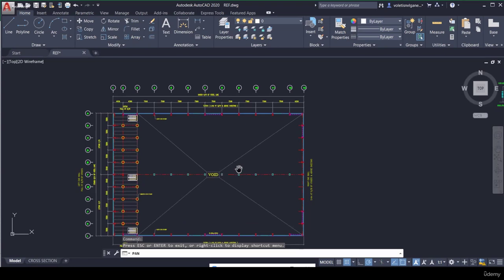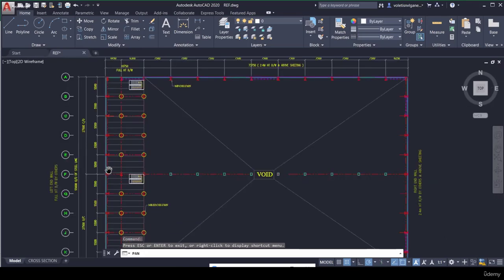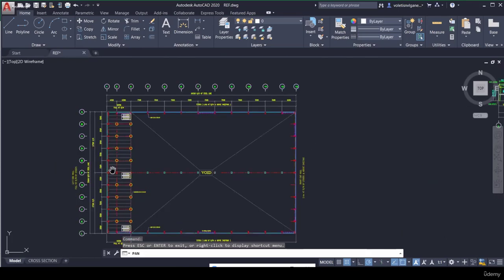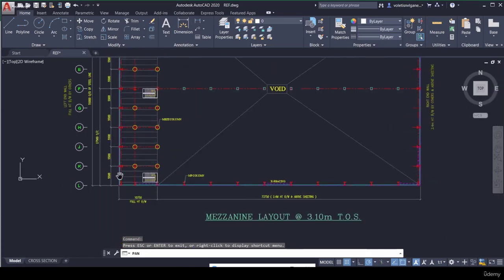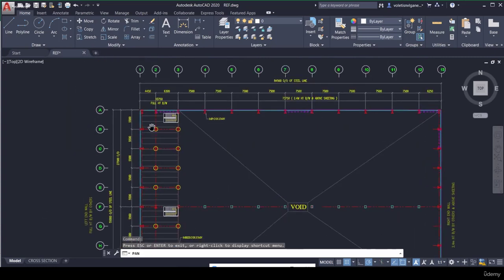Basically, end frames are of two types. One is the main end frame and the other is the light end frame. A main end frame is one where no bracing is allowed between the internal columns. In that case, we call it a main frame. Otherwise, if bracing is allowed, it is a light end frame. Generally, why do we provide bracing? We have to provide bracing for control.